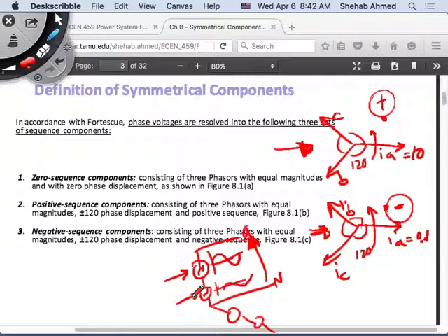But what will that do to the motor? Again, at the end we want to produce torque. I don't think it will slow it down, because at the end of the day we have the same frequency. Typically, frequency is what is proportional to speed. Torque is proportional to the flux in the gap, and the flux in the gap is typically proportional to V over F. So now I've added flux components due to a positive sequence and flux components due to a negative sequence at the same time.